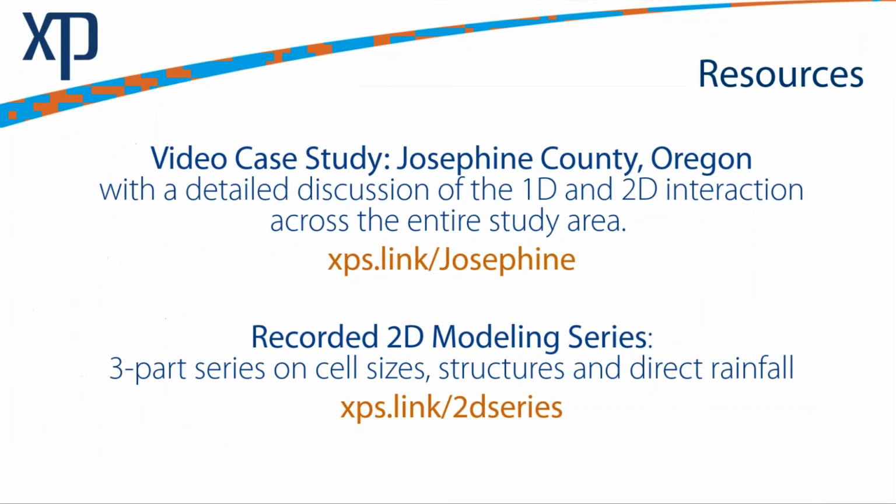So just to sum it up, we talked today about some different aspects of 1D, 2D modeling. I think the important ones were how 2D is different in the way we treat storage, how we treat hydrology, and then how we link up the different types of models that we're running, 1D and 2D, so that they all run together and they're linked in time and they're exchanging with each other in a realistic fashion to produce realistic results.